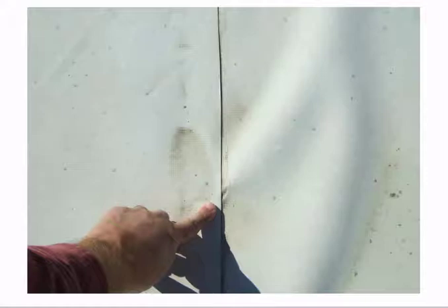Be sure to use membrane in the field of the roof. You have to use field membrane, so you can't use the uncured membrane for this. Yep. And the other thing that we see all the time is they'll come in and just try to re-weld it. Rather than being over-welded, they might think it was under-welded, didn't get the right bond, and you'll just see them try to re-weld that. But to Craig's point, you want to do a nice, solid, long-term repair. Yep.